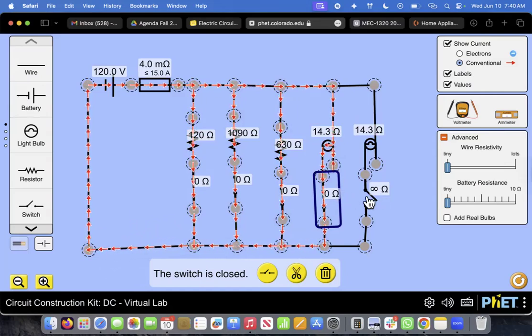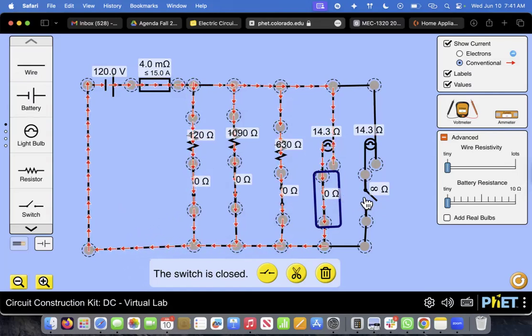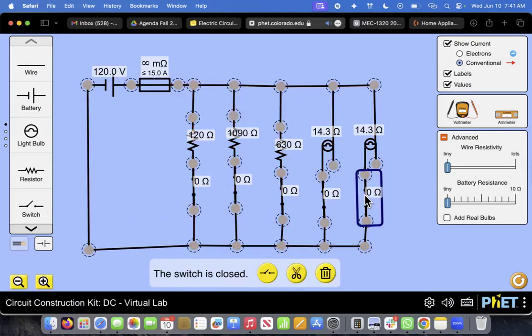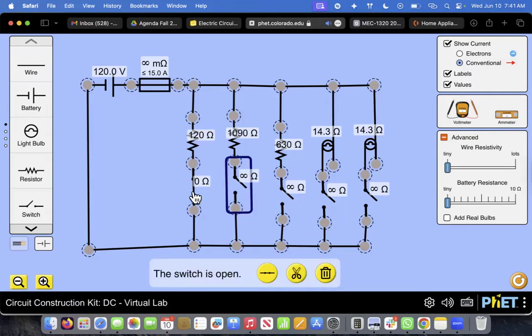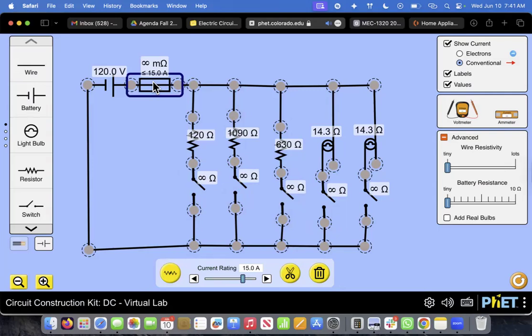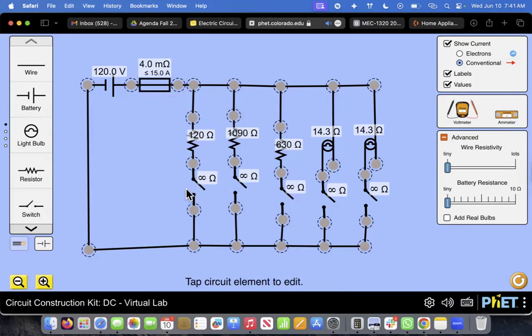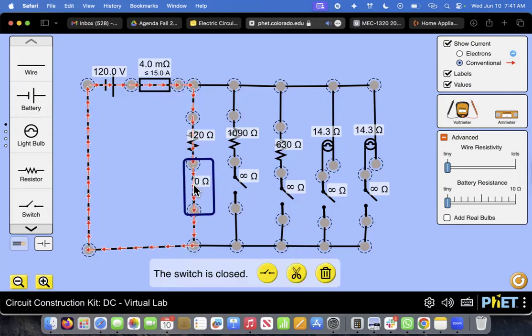And then if I go to turn on the coffee maker at the same time, so this could be like a Keurig. It only operates for a minute, but if these two happen to be on at the same time, let's see what happens. Oh, okay, and everything shuts down. And we don't get all the lights go off because the circuit breaker is controlling the current through this entire circuit. So let's see if we can turn this back on. I don't know. Looks like it's broken. Now it's back. Yeah, there we go. Okay, now I reset the circuit breaker and now the lights are back on.